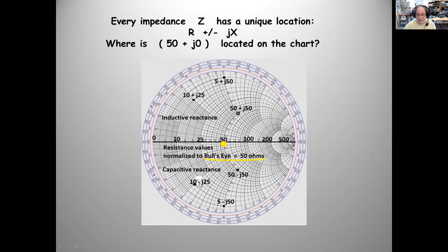Well, it's basically the same thing except they're negative J, meaning a capacitive reactance. So fundamentally, you give me any reactance value, anything, it'll plot somewhere on here. Now it may plot way over at this end or way over at this end. They're sort of equally bad. You want to be close to the bullseye for 50 ohm radio, 50 ohm coax, 50 ohm antenna.